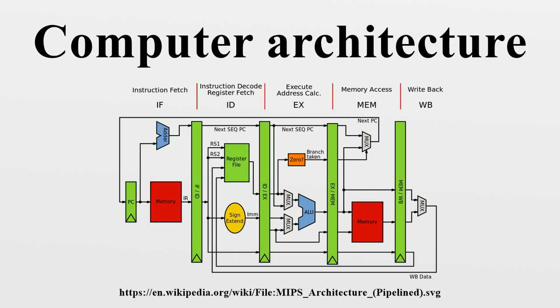Physical implementation draws physical circuits. The different circuit components are placed in a chip floor plan or on a board and the wires connecting them are routed. Design validation tests the computer as a whole to see if it works in all situations and all timings. Once implementation starts, the first design validations are simulations using logic emulators. However, this is usually too slow to run realistic programs.